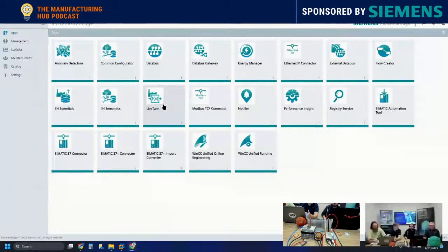Really? Interesting. And I can do it at low latency because I'm directly next to my PLC. So I'm not running my cloud simulation up here and I have 1 second down, 1 second up to get any sort of response. I'm right close to the machine, so I'm down at that 100 milliseconds up, 100 milliseconds down for my latency.